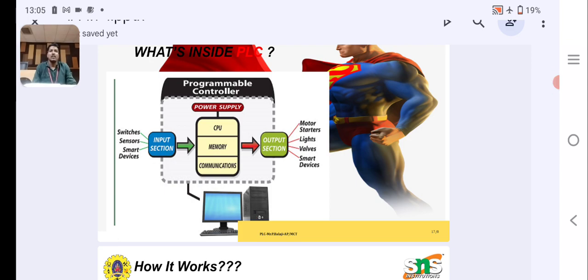The internal paths along which digital signals flow are called buses. In the physical sense, buses are just a number of conductors along which digital signals can flow. They might be tracks on a printed circuit board, wires, or ribbon cable. The CPU uses the data bus for sending data between constituent elements. The address bus carries the location address, to locate data stored in memory. The control bus carries signals for setting internal control actions. The system bus is used for communicating between the input output ports and input output units.